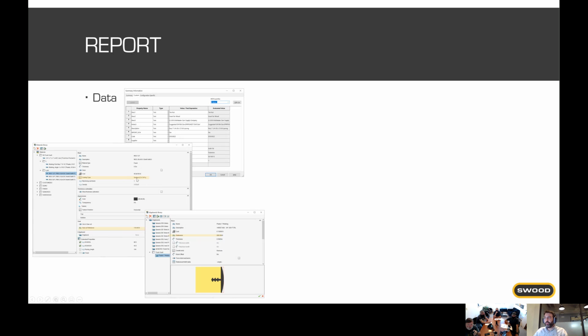And we will also use the costing type between surfacic. So for LW, I use surfacic. For L, I use linear cost. And for the other parts, standard parts, I use unique cost. We have also additional things and information, for example, the board dimensions that I will use for the surfacic to directly divide the information, the buying length for the linear as well, and same thing for the edge bands.